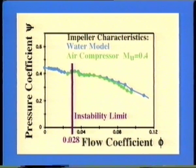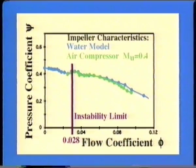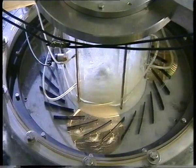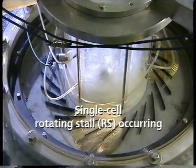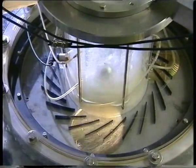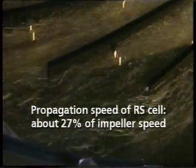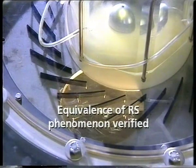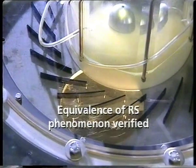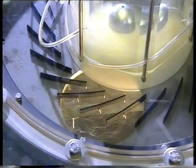Rotating stall develops at the same flow coefficient equal to 0.028. Single-cell rotating stall occurs in both rigs, and the stall cell propagation speed is about 27% of the impeller speed in both rigs. With respect to rotating stall, one can conclude that the air compressor and the water model are hydrodynamically equivalent.